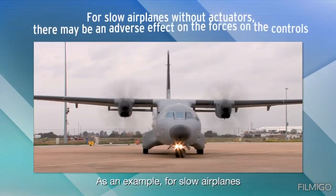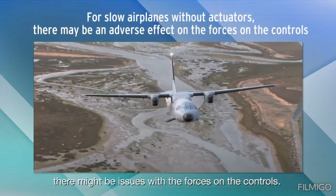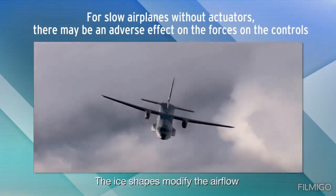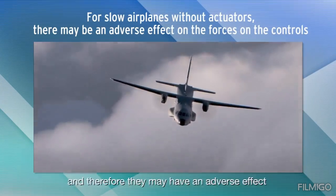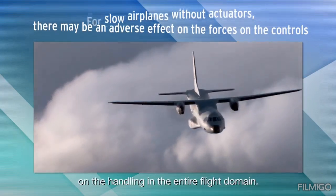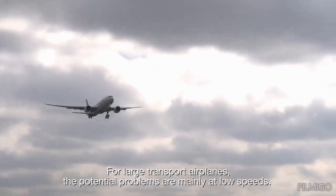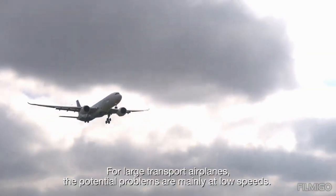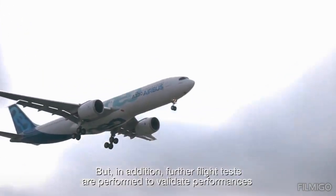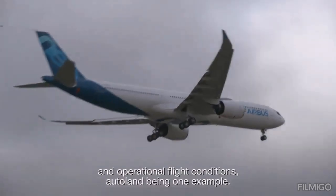As an example, for slow airplanes with flight controls not equipped with actuators, there might be issues with the forces on the controls. The ice shapes modify the airflow, and therefore they may have an adverse effect on the handling in the entire flight domain. For large transport airplanes, the potential problems are mainly at low speeds. But in addition, further flight tests are performed to validate performances and operational flight conditions, autoland being one example.